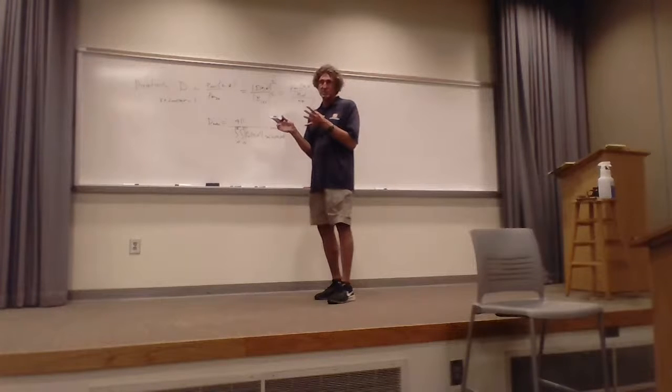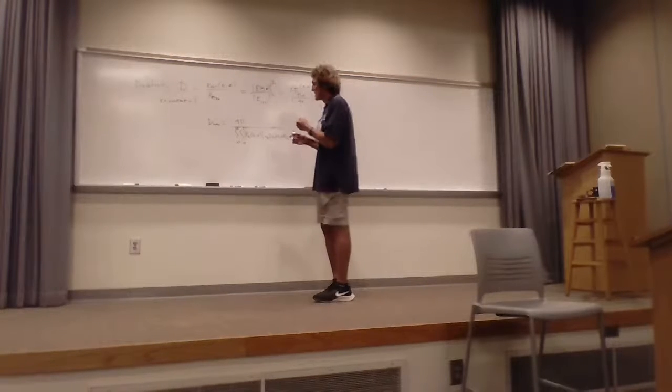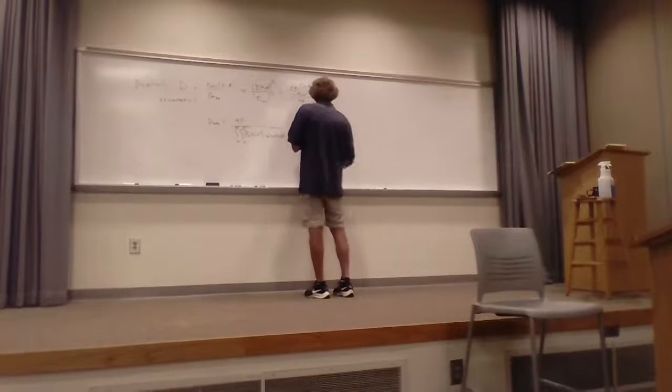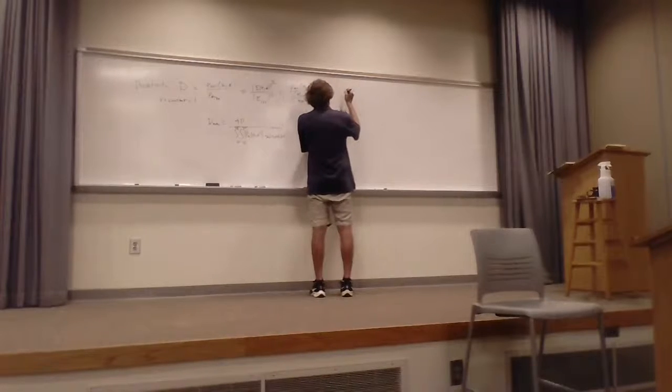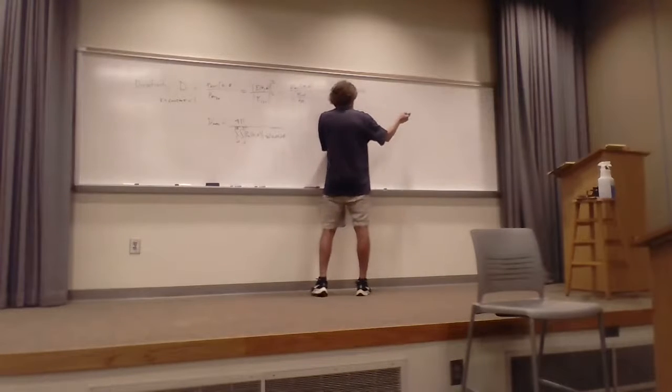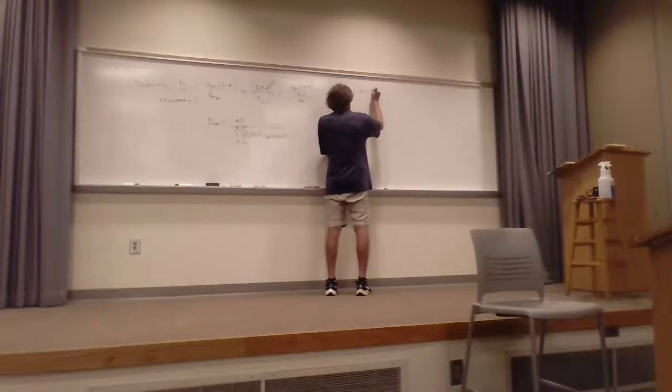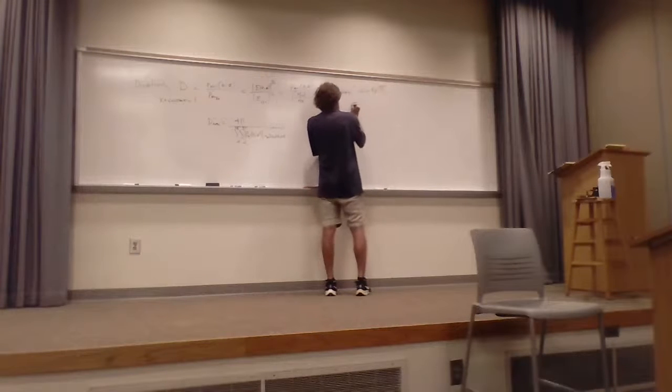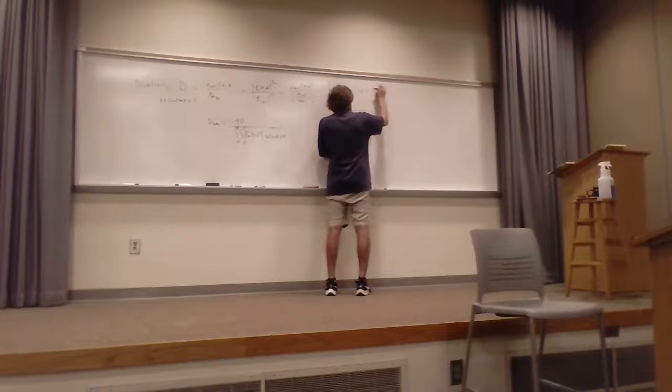Directivity is always used this way, but really, the thing I like to think about is something called gain and directivity. They're linked. And write this down now. He doesn't do it, but I'm going to tell you it's better to do it this way. The antenna gain, symbol for that is G. And G is really equal to the efficiency of the antenna times the directivity. Now, I mean times D, right?